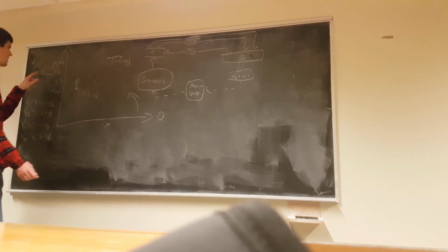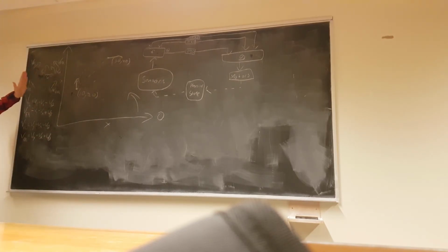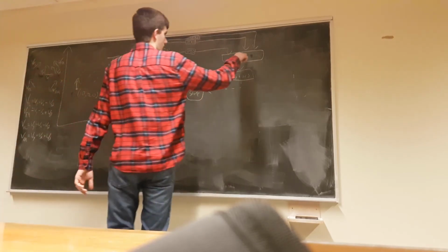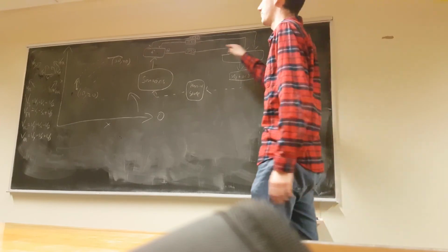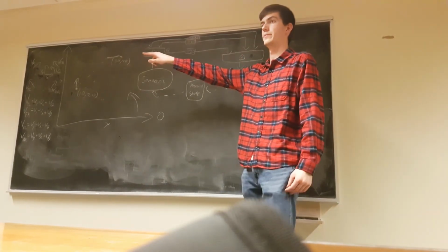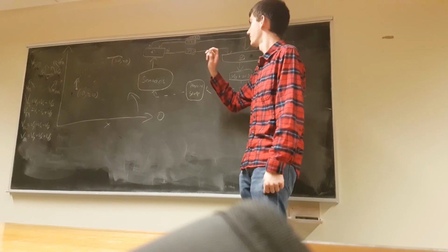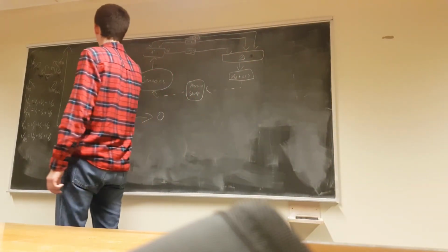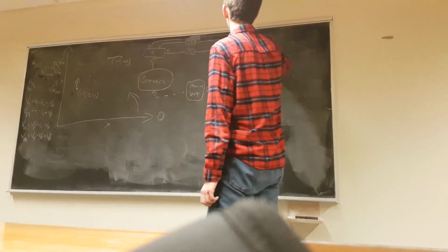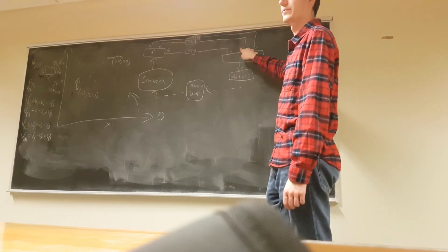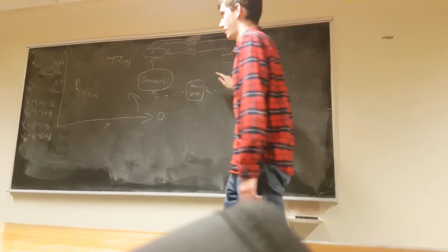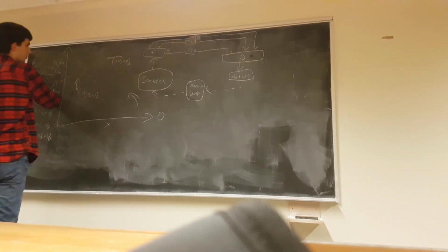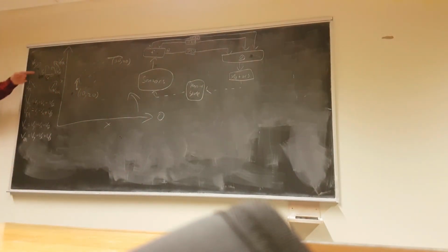So that's how we get, if we have an x, y, and theta, and remember x represents left, right, y represents forward, backwards, theta represents turning, that's how we turn that into motor velocities. There's one other step that needs to happen though, because we can't just plug this in there. Can anyone tell me why? If we want the robot to go that way, we'll have a large positive value here from y, right? If we plug a large value into here, what does that do to the robot? It goes forwards. Which way is forwards? Depends on the orientation.